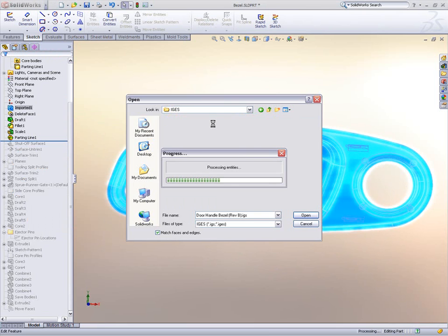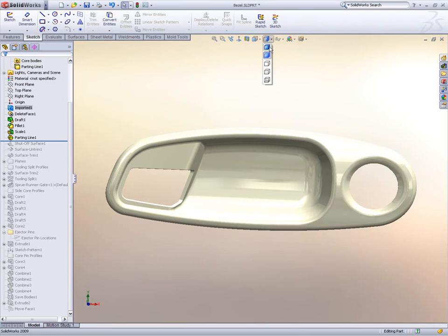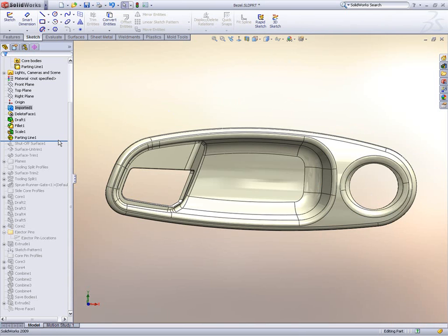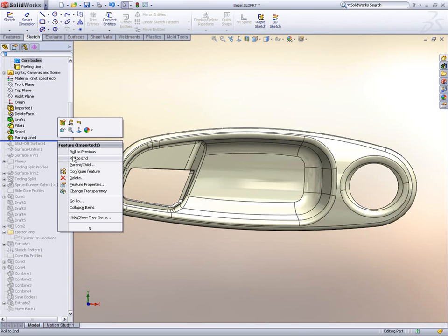If a change conflicts with the previous design and requires a new parting surface or side core, SolidWorks will indicate any potential errors and try its best to rebuild the mold. Problem areas can then be fixed manually until the mold is working as expected. The good news is that you won't have to start from scratch, even with the toughest of design changes. This change in geometry does not affect the split line or the shut-off surfaces, so we're in good shape to let SolidWorks rebuild the rest of the mold features we made earlier.